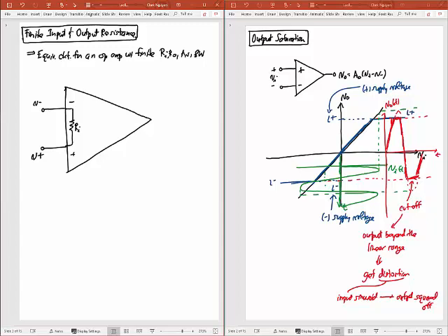Okay. If it also has finite output resistance, then instead of going straight to the output from my voltage source, you know you have a controlled voltage source. I'll draw that right here. So that's plus and minus. We still have that controlled voltage source that goes from ground up to this output node. And that still has, if it's finite gain, the transfer function A sub V, the gain of the op-amp.